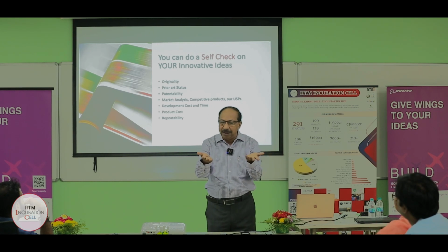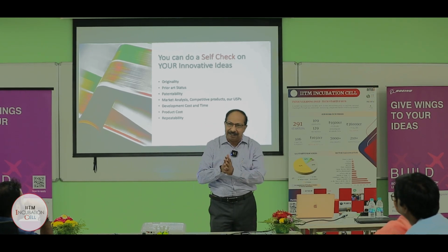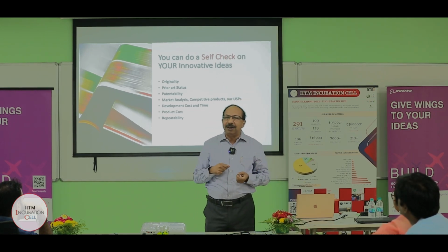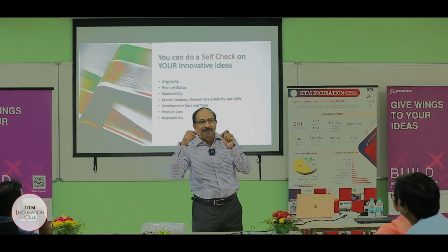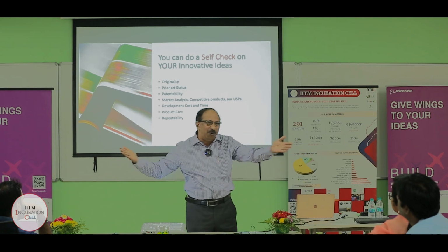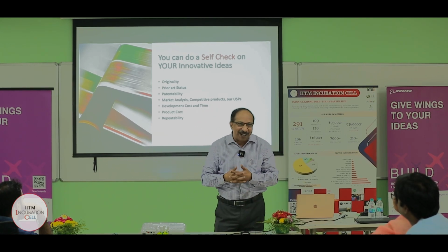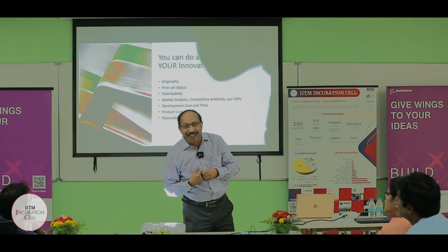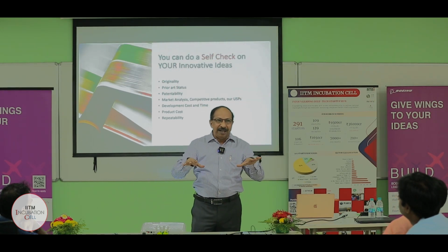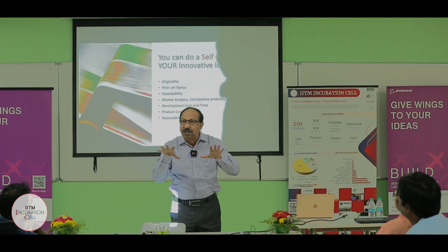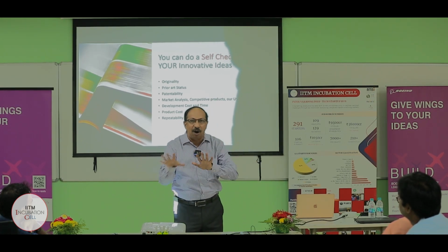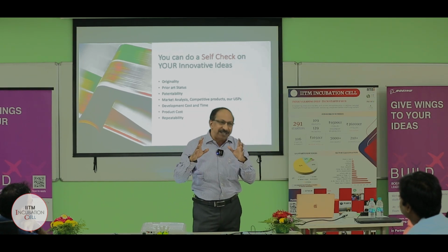I am talking about electronics, but it is true for mechanical or any other thing. One example I will just give. The resistor, those who are electronics engineers, we have a resistor and we have a tolerance ring. The tolerance ring, gold ring, silver ring and all, long back, I don't know whether you have really used it after BTech first year or even pre-degree class, why that is required and all. But when you are designing a product, you have so many components with these tolerances. It can happen that your amplifier may oscillate because of all these tolerance issues. So you have to really do a tolerance analysis.